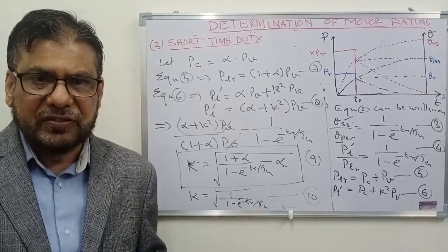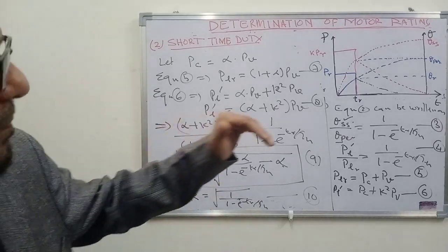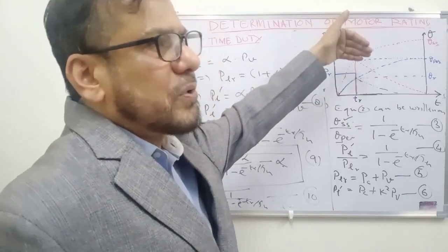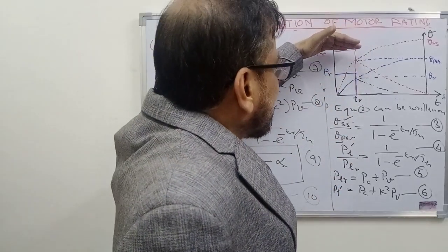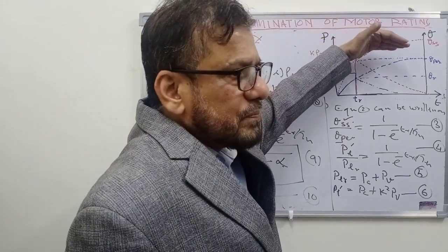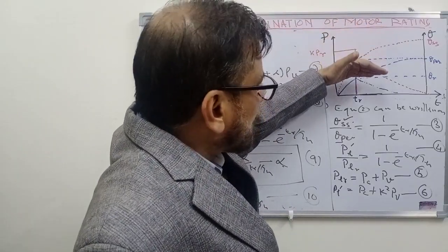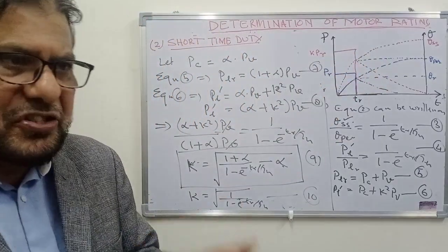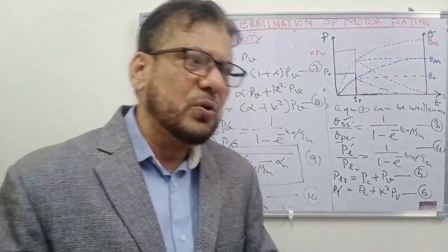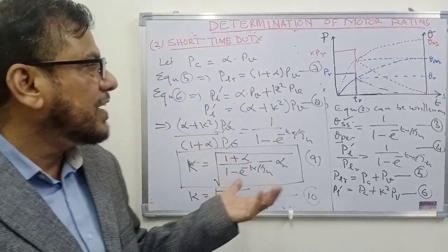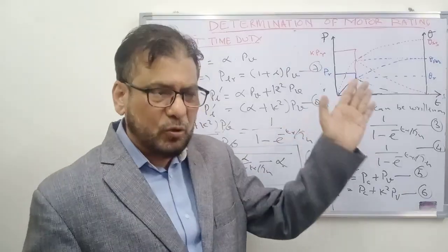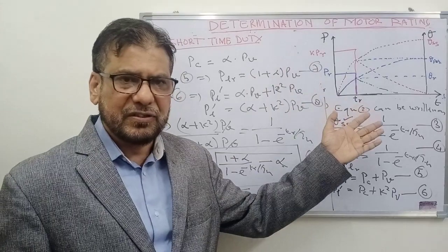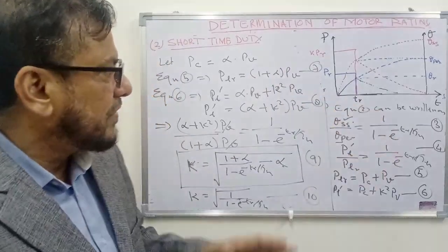So in that way you can select a motor of a lesser power rating and you can overload the motor as per the required load. This was the rated demand of the load, and you have chosen a motor of lesser power rating. In that way you are reducing the initial cost of the motor without overheating it, without sacrificing the life of the motor. The motor will run its normal life. If it is to last for 10 years, it will last for 10 years. The life will not reduce.